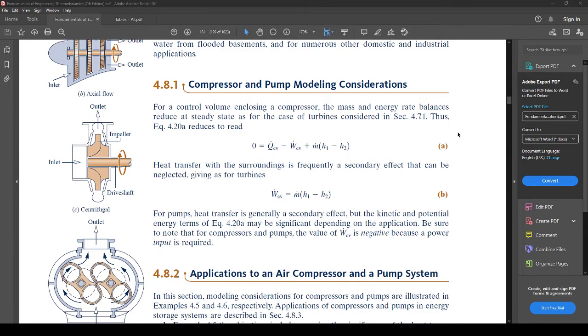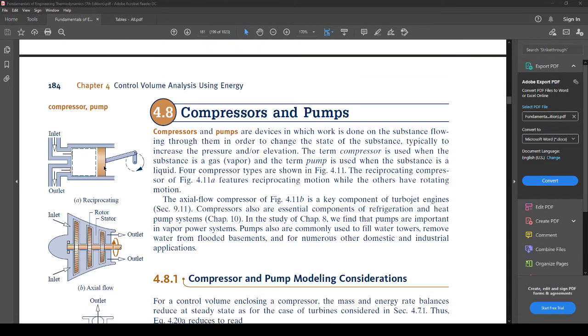So then we have compressor. These are all the ones they were talking about here. This right here is the reciprocating one. Essentially as this thing spins, it's pumping it in, drawing it in, right? So this is a valve right here. It kind of reminds me a lot of a car engine, right? Essentially as this thing retreats or comes closer, it pulls in more and presses it. Whenever this thing draws back up, it pulls all this in and then it presses it into a smaller area right here, and then this valve opens up.